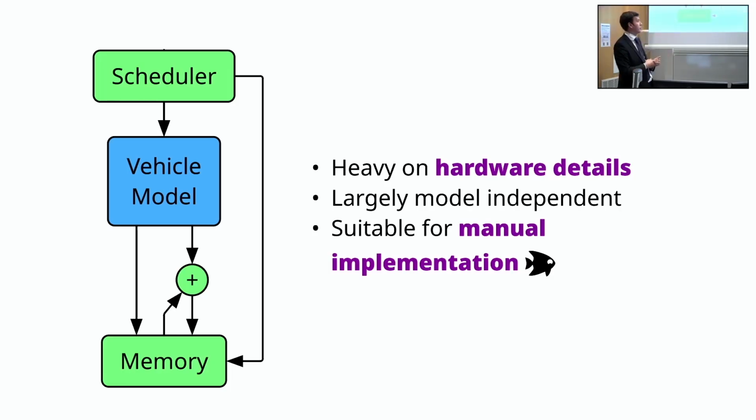And so that's the workflow we propose, and we show that by doing this, high-level synthesizing the vehicle model, and then manually implementing the scheduler and the memory, we can accelerate this computation, run it in these 2 seconds in real time, and we can even do it in a configurable way, so you can have a configurable number of instances of the vehicle model to tune performance versus resource usage.